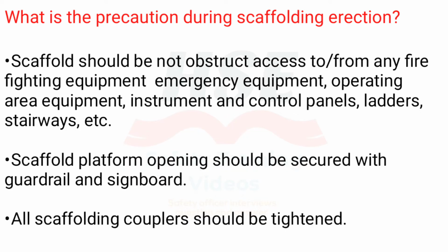Scaffold should not obstruct access to or from any firefighting equipment, emergency equipment, operating area equipment, instruments and control panels, ladders, stairways, etc. Scaffold platform openings should be secured with a guardrail and signboard. All scaffolding couplers should be tightened.